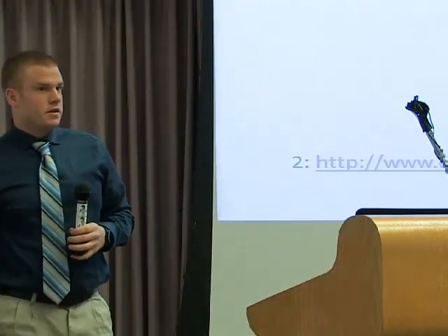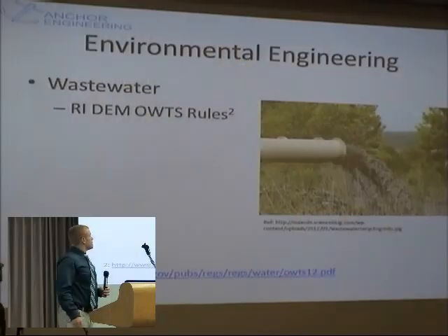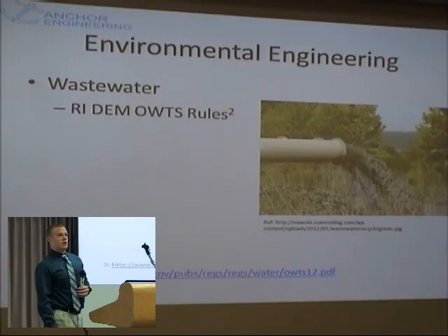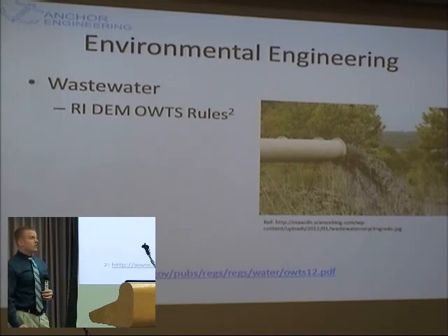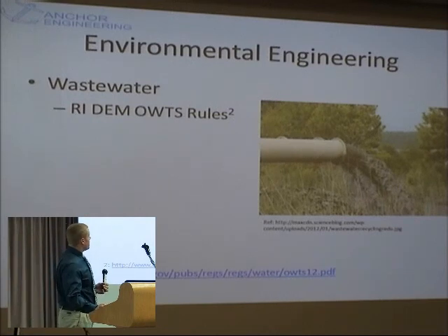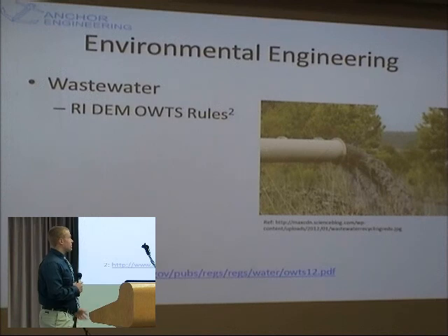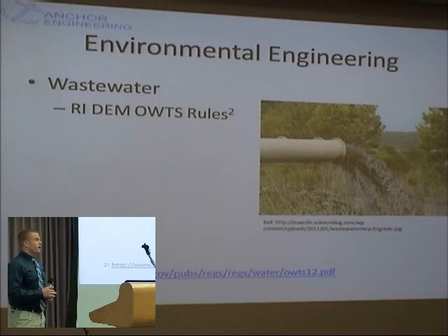Alrighty, as the environmental engineer, my second main focus was wastewater management. We had 2 options. We could treat the wastewater on site, or we could pump it to the main sewer line. Due to the industrial loading and the large loading from the restaurant, we thought it would be best to pump it off to the sewer line. My main set of rules and regulations came out of the Department of Environmental Management's on-site wastewater treatment systems rules. Though we pumped it, a lot of our calculations we had to get from this manual.